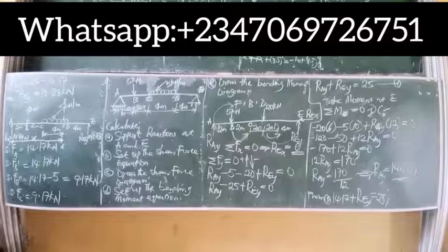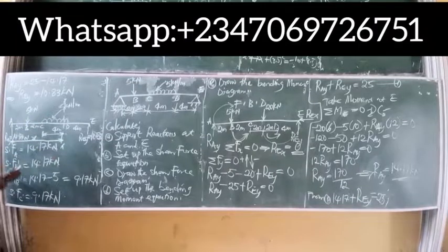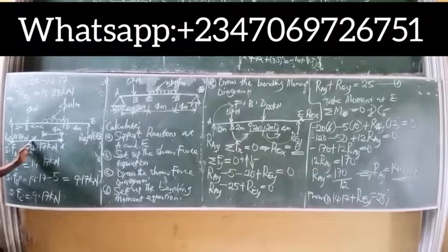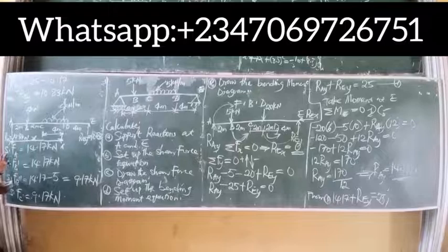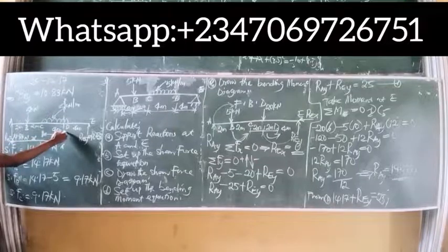Because we have a different kind of loading on the beam, we have to form an equation. To form this equation, due to this UDL, we can simply take a section along the UDL, which is along CD. So you consider a section XX at a distance of X from A. So always that distance from point A to the point of section remains what? X. Okay, so if that's the distance, what is now the distance of this UDL from point C to the point of section?